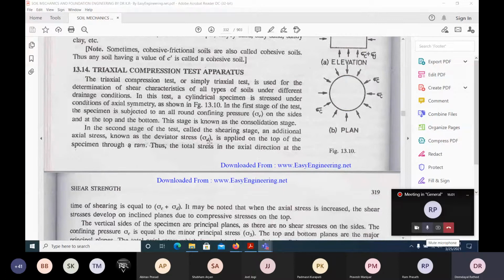These are all based on pore pressure measurement, and we can do many things using the triaxial test. We can measure the pore pressure developing in the soil, check the failure, allow the water to dissipate, or sometimes stop the water. So we can play with it.